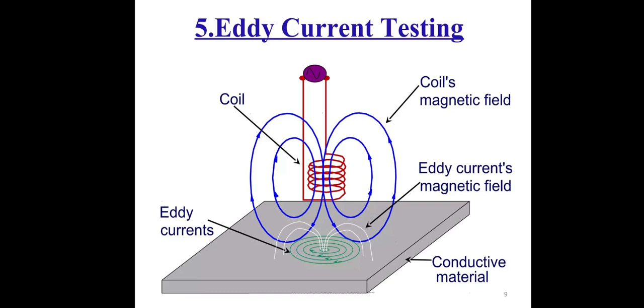The defects in the test object impinge and change the direction of eddy current and cause changes in the electromagnetic field. These changes affect the inspection coil, the voltage of which is monitored to determine the presence of a defect. The image illustrates the effect of a crack on the pattern of eddy current flow in a plate. The plate travels along the length of the inspection coil as shown in the figure.